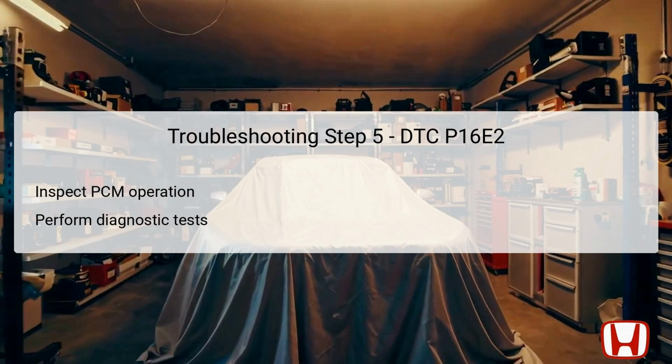communication with other components. If the PCM fails tests or shows persistent error codes, replacement may be necessary to resolve the issue effectively. It's vital to ensure that all aspects of the troubleshooting procedure have been completed to avoid premature replacement of the PCM without addressing underlying issues.